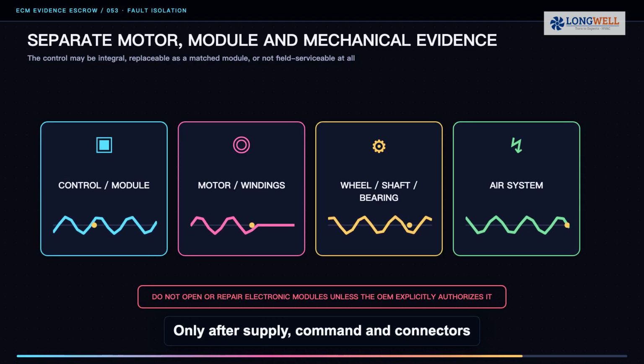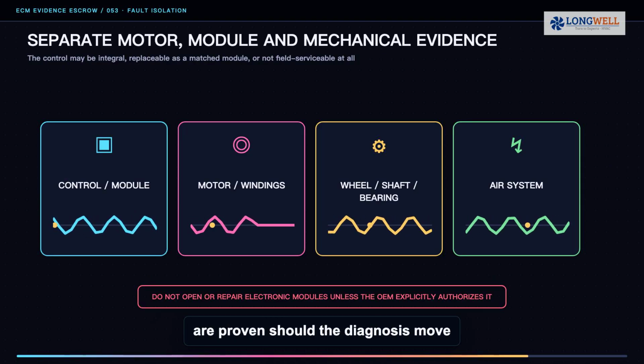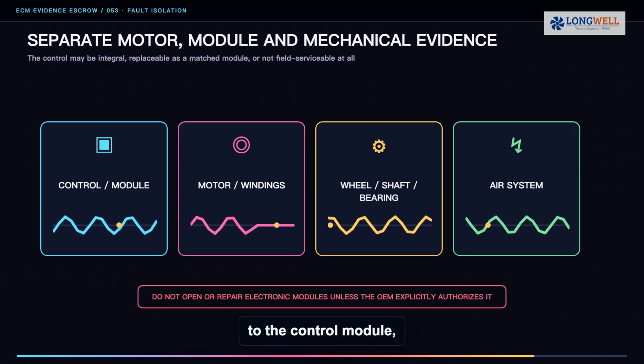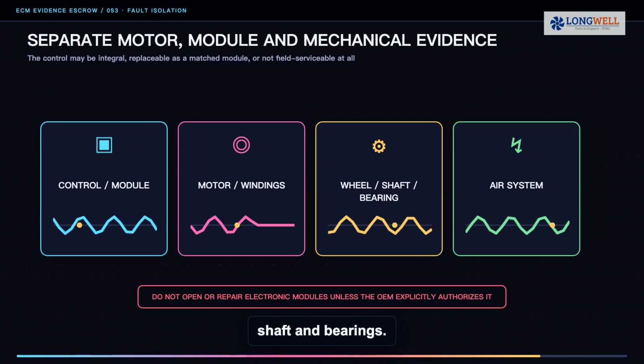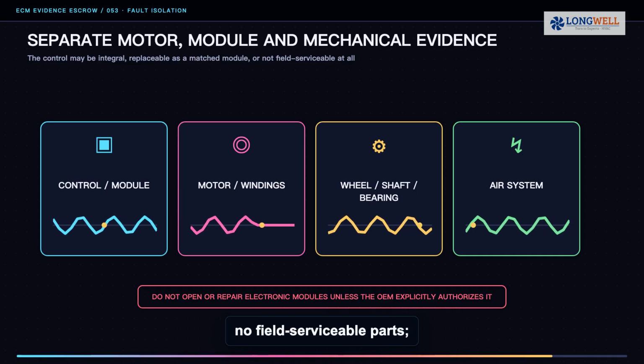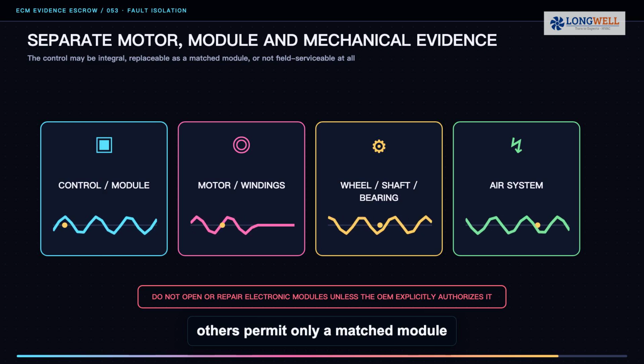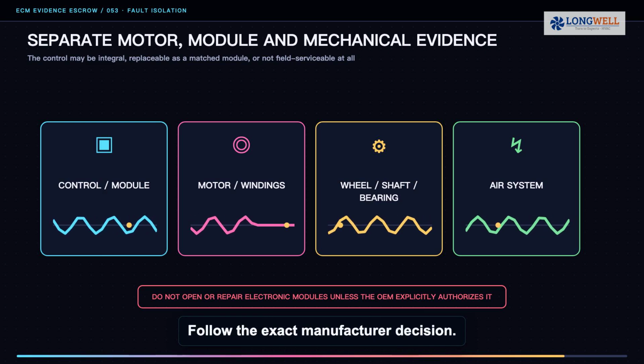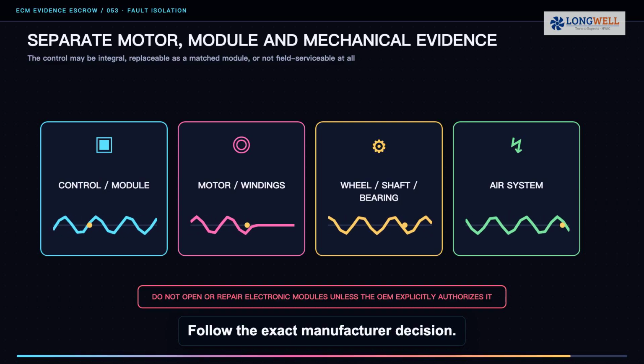Only after supply, command and connectors are proven should the diagnosis move to the control module, motor windings, wheel, shaft and bearings. Some controls are integral and contain no field serviceable parts, others permit only a matched module replacement. Follow the exact manufacturer decision.